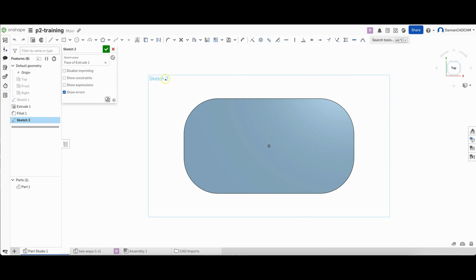And here we select circle drawing. Choose the center point circle command. And here I would like to place the center of the circle at the center point of this fillet. As you can see, when I hover over this fillet and then hover near the center point of this fillet, a snap appears here, and we also have a constraint icon. This means that if we click here, the center of the circle will be constrained concentric to the fillet. I left-click, then I left-click again to specify a point on the circle, and for the circle diameter, I enter, for example, 12 millimeters and press Enter.